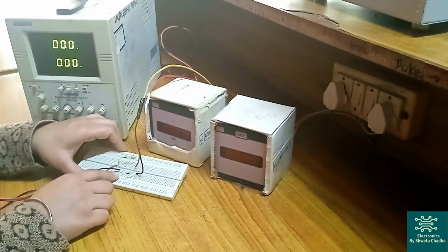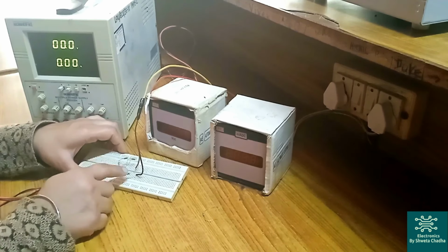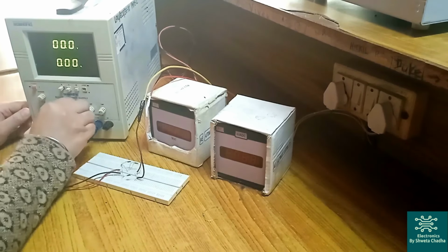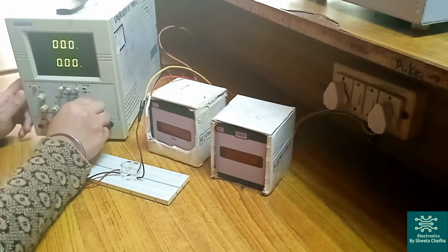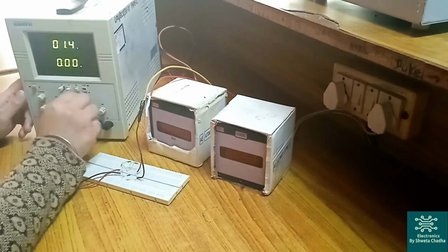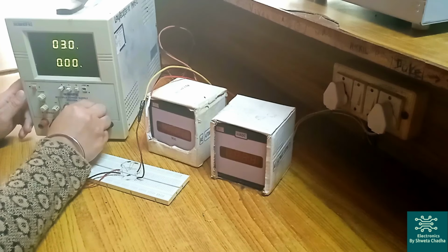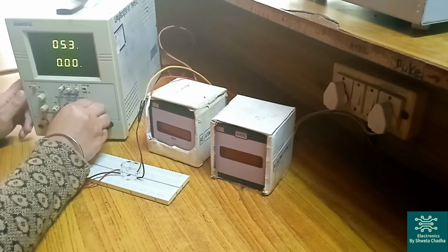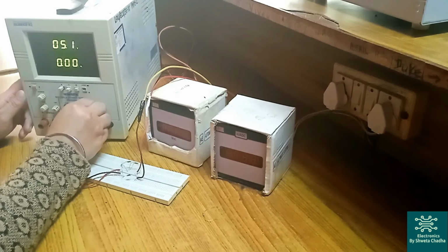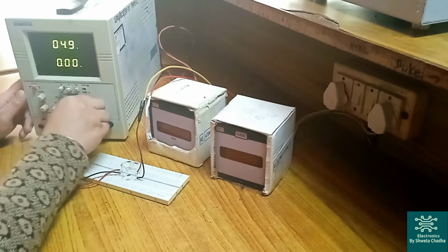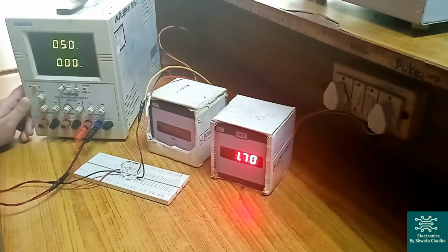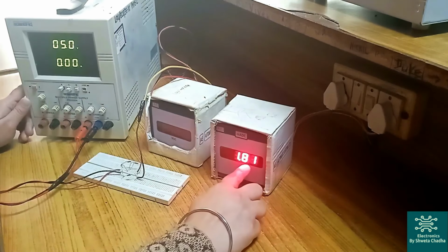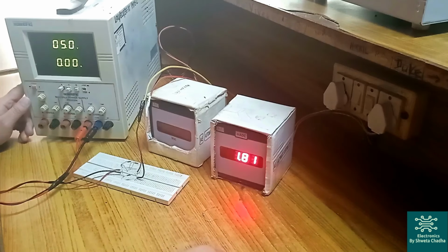So again you can have a look. I have connected all these connections in a single column, and the input must be set to 5 volt. Right now I am using channel B, so channel B must be pressed. Let us increase the voltage to 5 volt. So the input has been set to 5 volt. Now let us switch on this ammeter. You can have a look: we have got around 1.81 milliampere as the step number 1 IL flowing through RL.